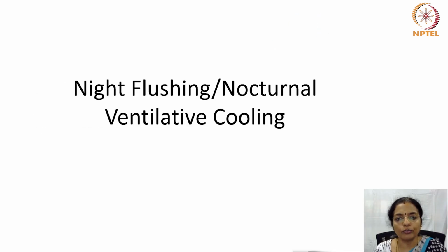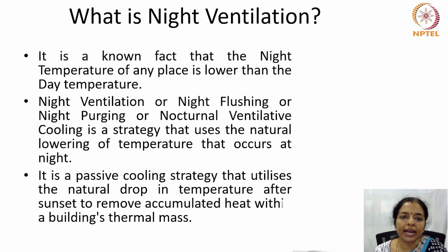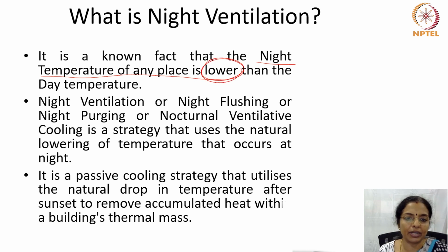So when we talk of thermal mass, it's very important for us to understand that nocturnal ventilative cooling clubbed with thermal mass can be a very effective passive cooling tool. So in this section, we will look at night flushing or nocturnal ventilative cooling as a passive cooling technique. So what is night ventilation? Now it is a known fact that the night temperature of any place is lower than the daytime temperature.